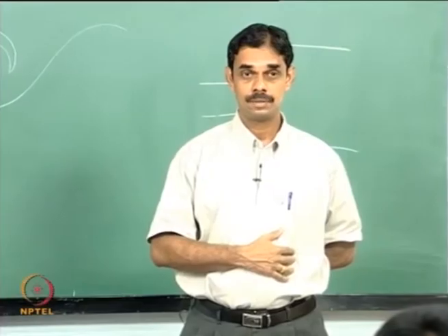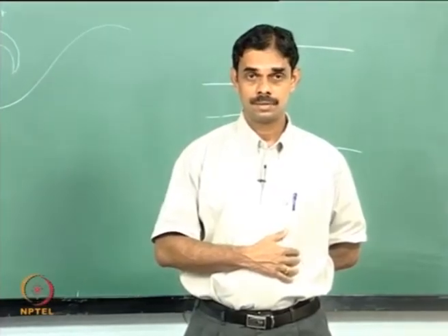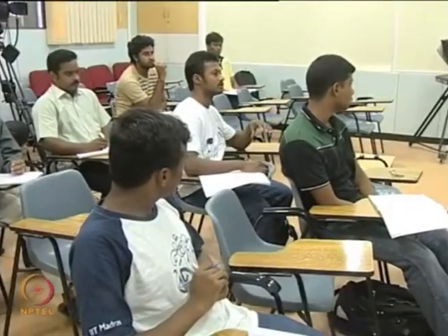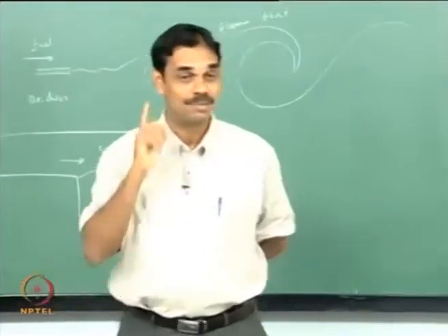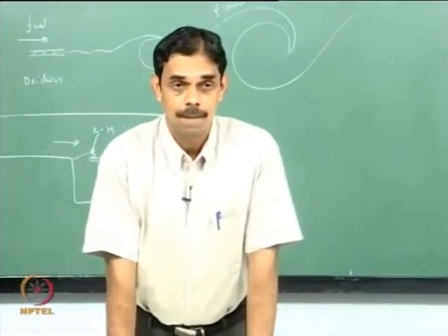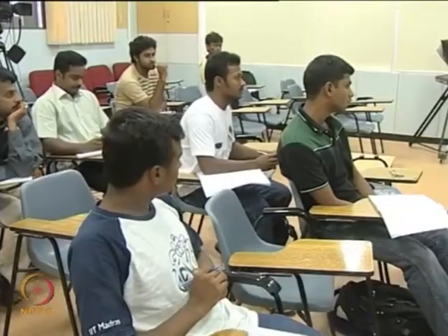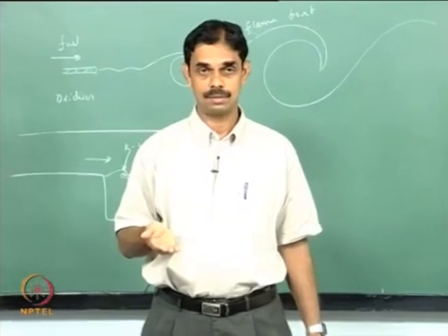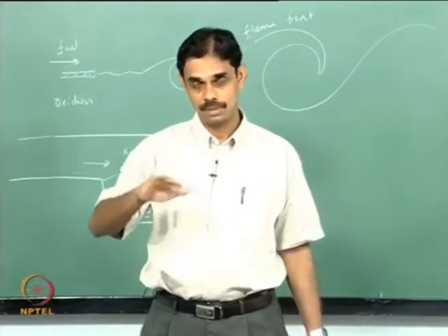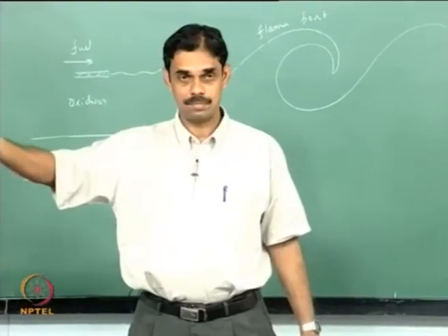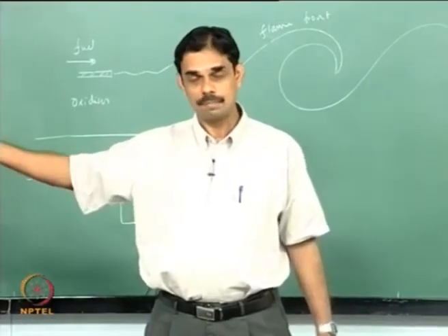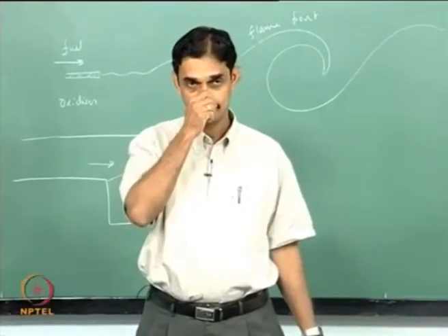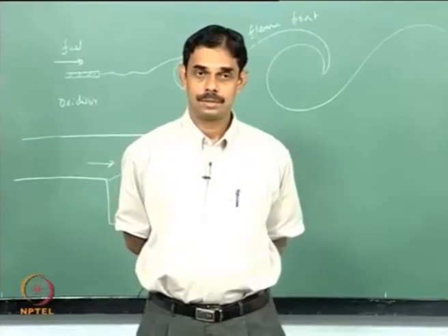The instability is basically from transition from laminar to turbulent. Only when the shear layers completely transit to turbulent. Can you repeat? You are asking a very deep question, so I have to pay attention. So the Kelvin-Helmholtz instability, it's basically during the transition from laminar to turbulent. No, you can have Kelvin-Helmholtz instability for laminar shear layers also. The shear layer will be unstable and roll up. In a practical combustor it will break down, but you can have it not break down also, and it is still Kelvin-Helmholtz instability.